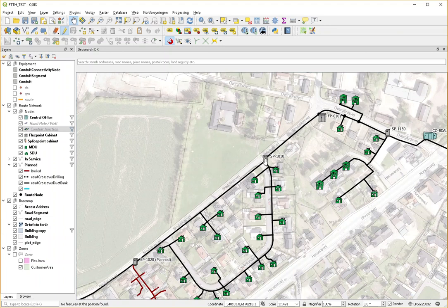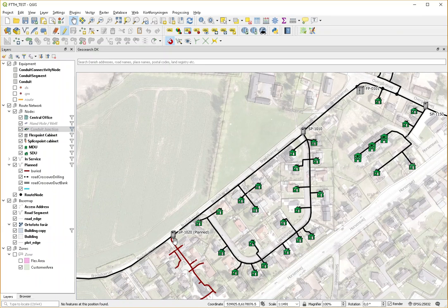For example, I blow one cable down here, and then I will connect these fibers to a fiber cable going into each house. Okay, but I will tell more about the fiber connectivity later. But you just have to know that the idea is when you place a new cabinet that you should be able to blow a cable from this guy here to this guy. So we need to find a pipe that's not occupied in this trench and make sure it's connected to this guy, so we can blow the cable, the feeding cable we also call it, to the splice point.